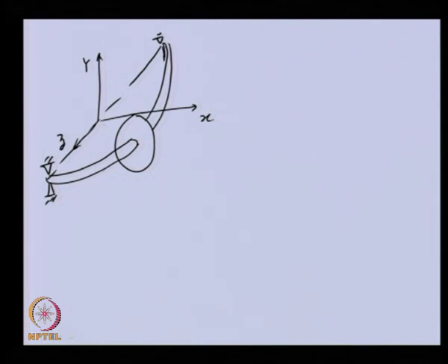The rotor has spin speed omega and is whirling about its bearing axis, the deflected shaft, at a new frequency, but we are considering the synchronous whirl condition. That means we are considering the whirling frequency equal to the spin speed, because the main force causing this is the unbalance.